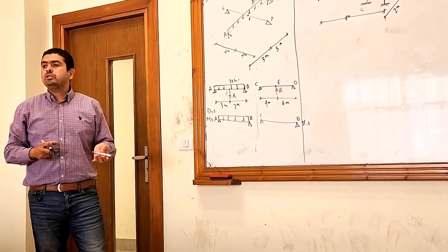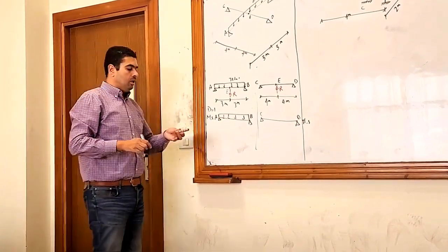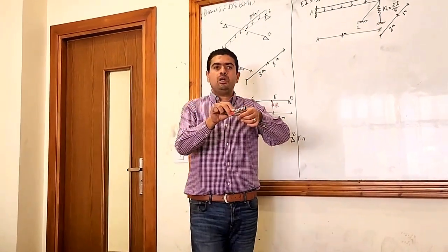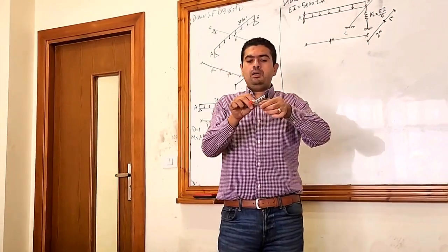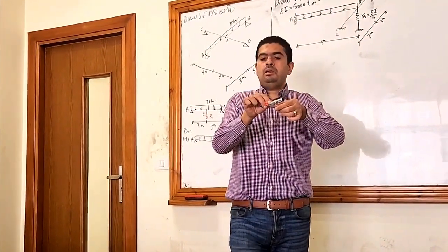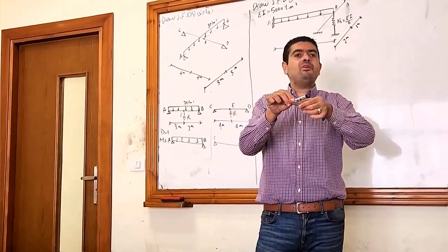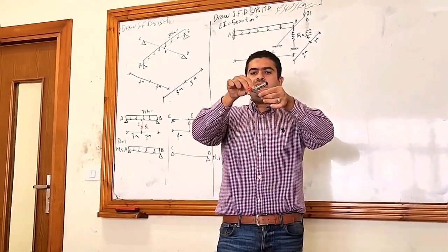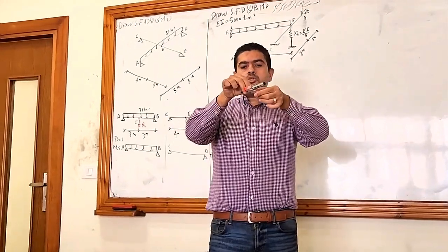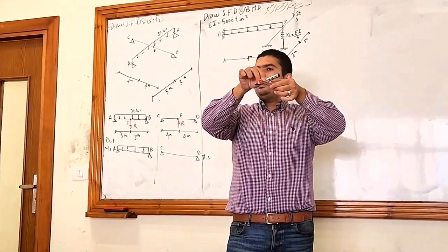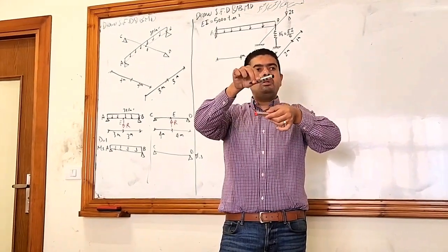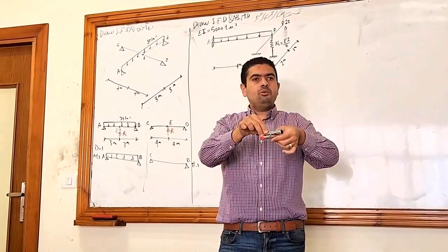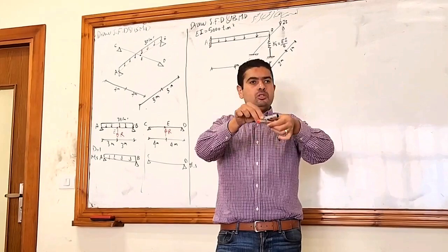Okay? What will be the condition? The same. There are two intersecting beams, one above the other. When point E has a vertical deformation, a vertical displacement, these are structure systems that are connected to each other, right? So when point E of the red pen goes down, will it go down individually by itself, or is this a connected structure? They will go with each other, right?